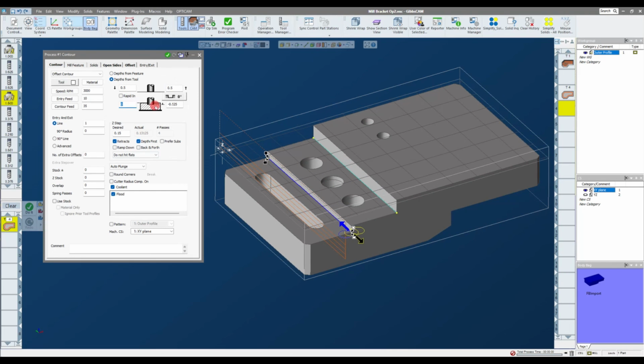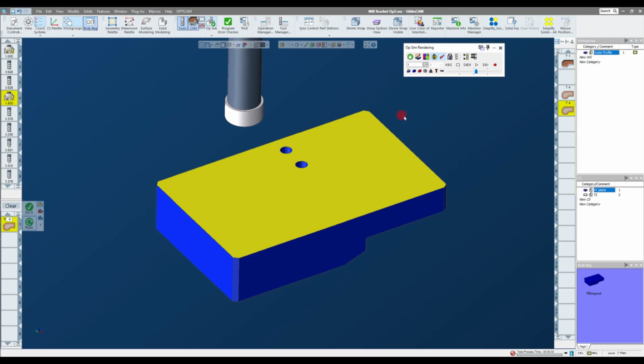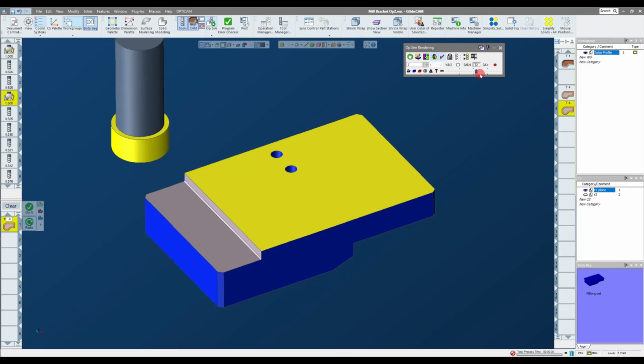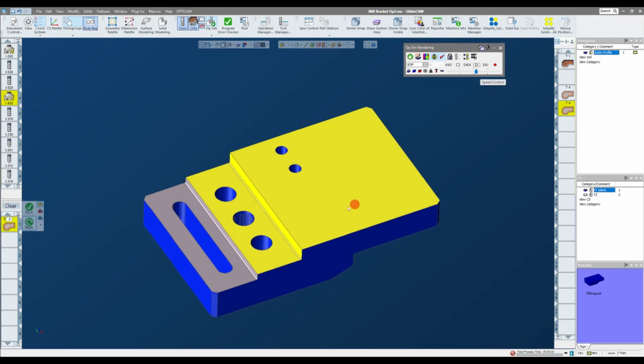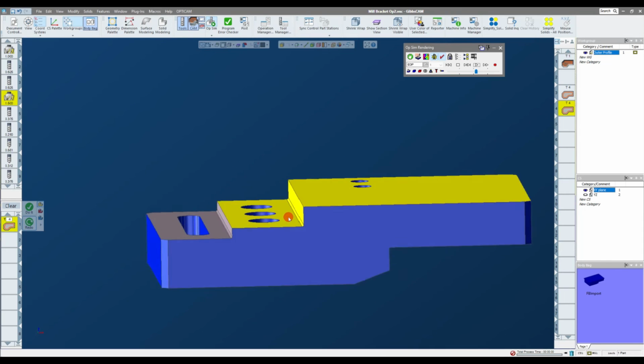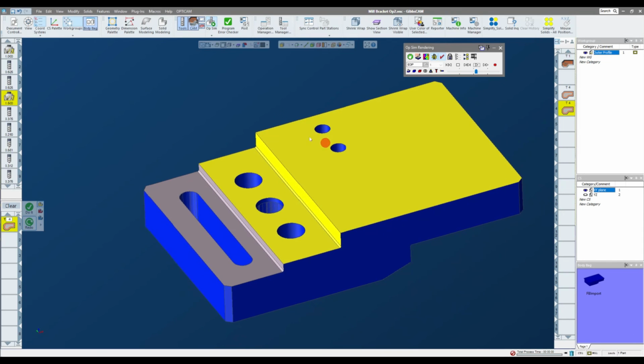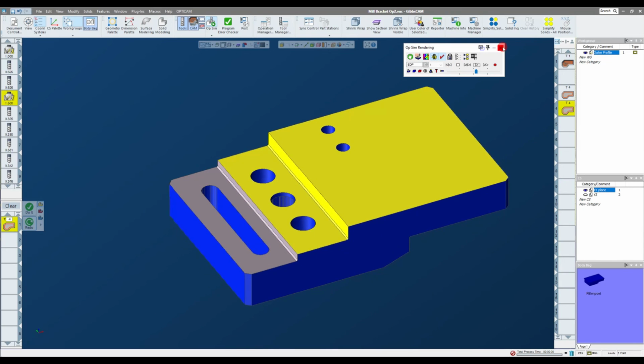The top of this cut's at Z0, the bottom of this cut's right here. I'll leave it at 0.15, same lead in, and there's no redo. I'm going to select a new piece of geometry, put it on the correct side, and do that. So there's my next step to cut. So if I run these next cuts, there's the first step, there's the second step, it's broken into. And I think that finishes our part.